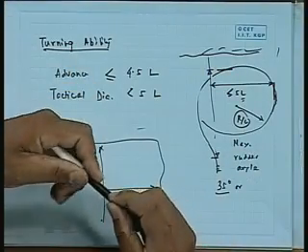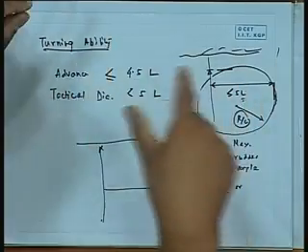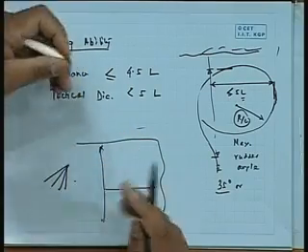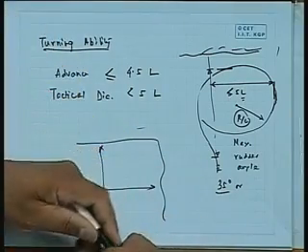There is a point at which no force has started acting. We'll talk next class about hydrodynamics of rudder. If you keep on increasing the angle, you have a plate here, you keep on making more and more, then it will not produce lift this side. It will be like a plane. There is a limit. If you want to go like that, it is not going to go up anymore because it is going to be just a drag. So for producing lift, you need an angle of attack. Normally they call it the angle of stall. After that, the lift actually comes down, and 35 also is very high.